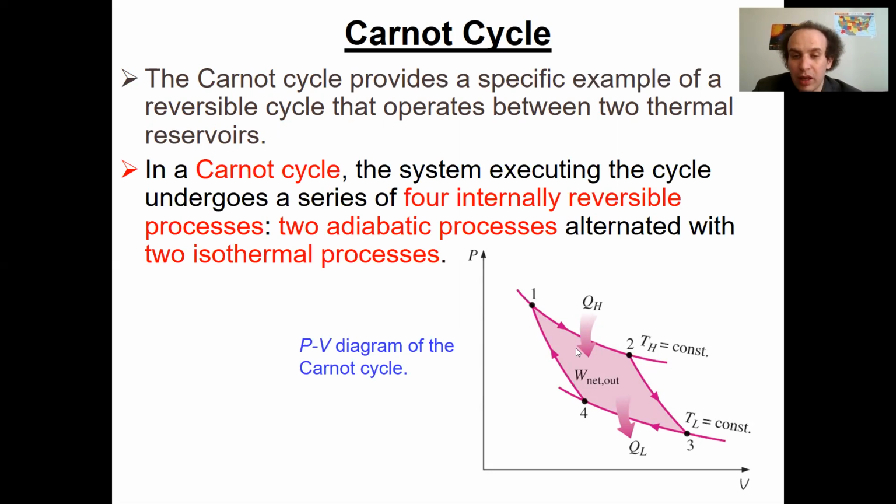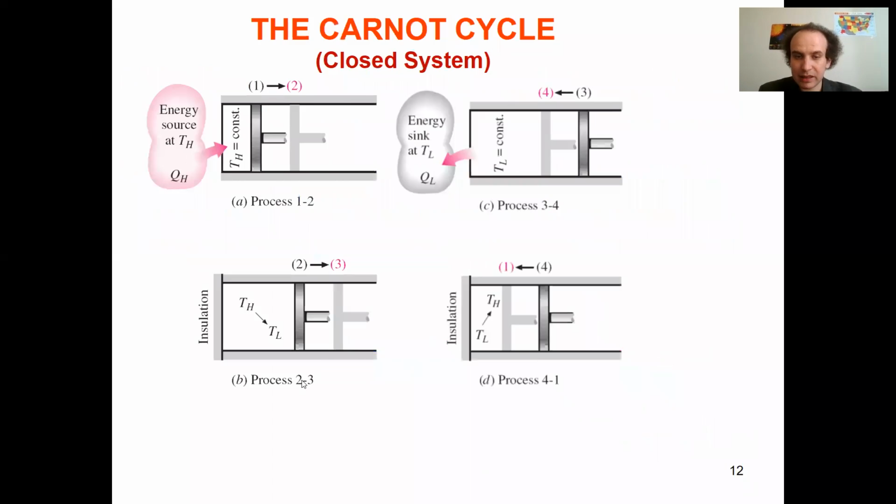Here we talk about a power cycle. When it goes clockwise it is a power cycle; if it goes counterclockwise, it will be the reversible Carnot cycle, you will realize. So now that's something important. This cycle consists of two adiabats and two isotherms. You must remember how this PV diagram looks. If somebody wakes you up overnight at 3 o'clock in the morning and asks, what is the Carnot cycle? You should say two isotherms, two adiabats. You must remember. Does it make sense?